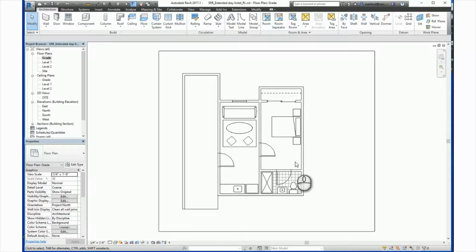The sketch stair is often used when creating custom shaped stairs. The stair by sketch method is also generally more complex, and we will cover stair by sketch methods in another topic. Both methods do require that you go to a plan view or a 3D view to create the stair. To create a stair element, we will need to provide information to Revit on basically three things, which we can find in the Properties palette.